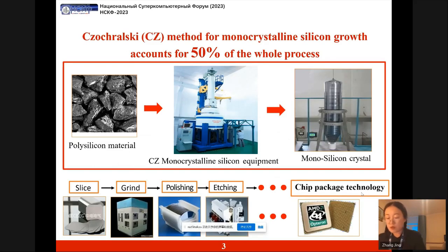Currently, the most productive method for growing monocrystalline silicon is the Czochralski method. When it was implemented into practice, it brought significant progress in the development of the artificial growth of crystals. The CZ process involves the transformation of polycrystalline silicon into monocrystalline silicon through crystal pulling equipment.